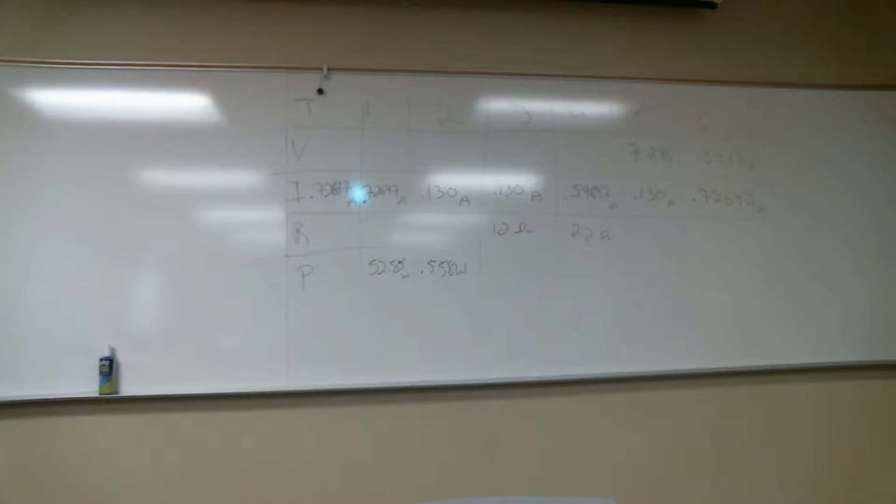I mean, for all of the different loads, I now have 2 ingredients. So I can calculate power and resistance for each one. Once I've done that, I can then back extract to voltage total. Or if I've got all the resistances, I could do the circuit analysis and get R sub T. Or since I've got all the powers, that's a straight adding problem. I can add all the powers up. In fact, I should kind of do all of those and then make sure the totals add up, and that would be my cross check, right? Okay, so from this point on, the problem should be pretty straightforward, right? Ohm's law. We don't necessarily need to do any more.